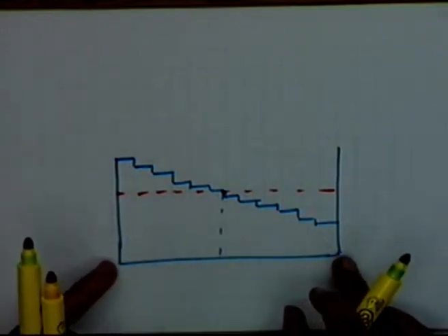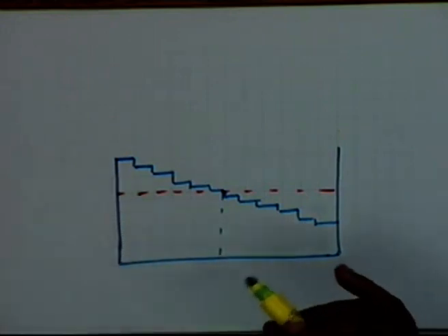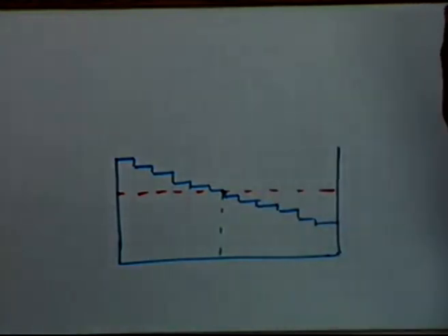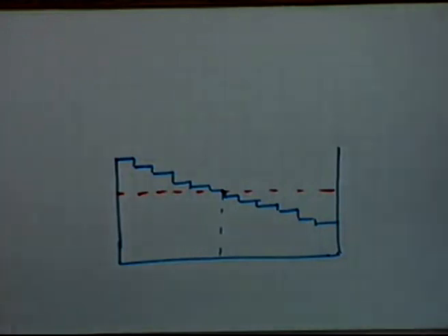This I am getting mainly because of the fact that the overlaps are not very accurate. They don't give me a uniformity coefficient which will ensure that at all the places I am getting the equal depth.